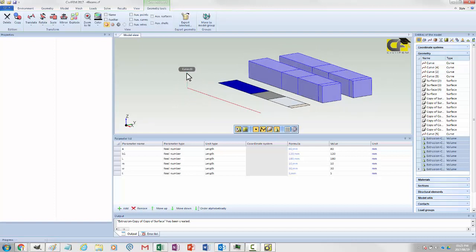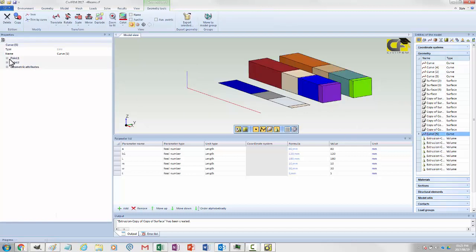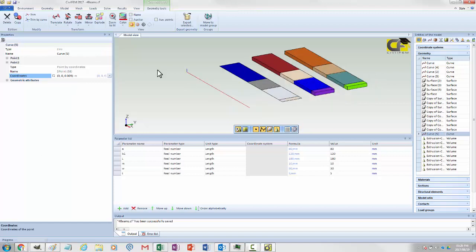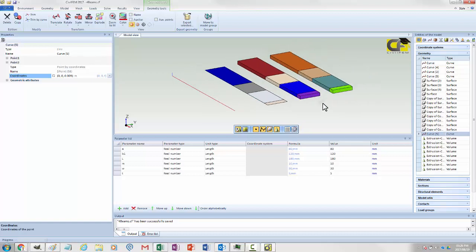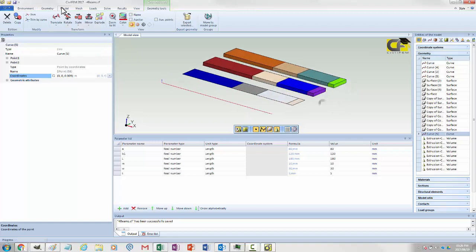We didn't need to define a thickness, so that's obviously not the correct way. So we can simply change that by changing 0.2 to be the thickness. Right, so we've reserved these curves for beam elements, these for shell elements. Now we're going to create tetrahedral elements and hexahedral elements in those solids.